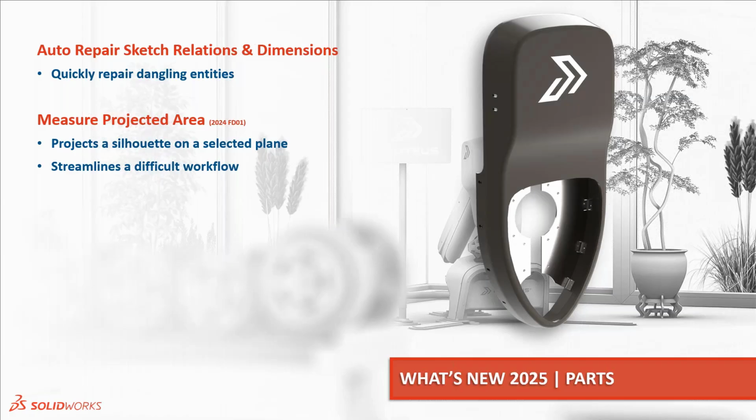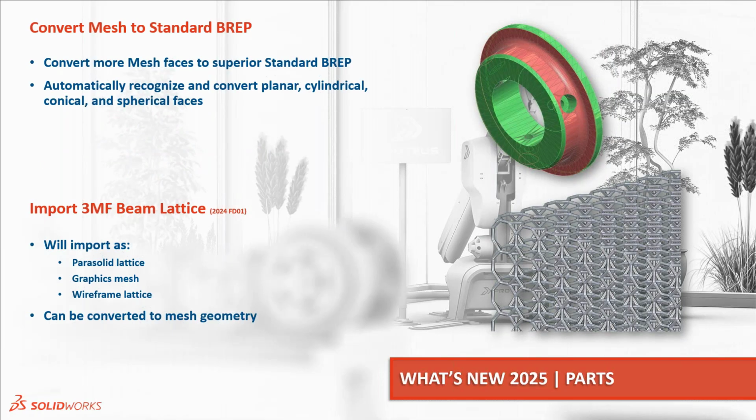We also have an announcement in Measure. Now we can measure projected area, which projects a solid onto a selected plane, streamlining a difficult workflow. We also have a few announcements related to mesh. Now we can convert mesh to a standard BREP. We can convert more mesh faces to a superior standard BREP. Automatically, we can recognize and convert planar, cylindrical, conical, and spherical faces. Now we can import 3D manufacturing format legacy files, which import as a Parasolid graphic wireframe. We can also convert it to mesh geometry.